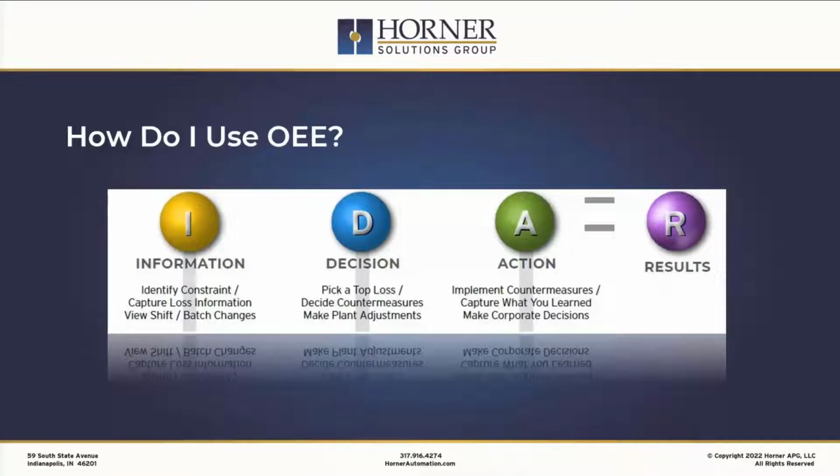And downtime is the one that's going to affect your availability for sure. And if you don't have availability, you can't make performance. So the downtime codes are probably the key to this whole process. And so having logged downtime and knowing when you're down and why you're down is a key piece of what the OEE allows to have solid data to make the right decisions.